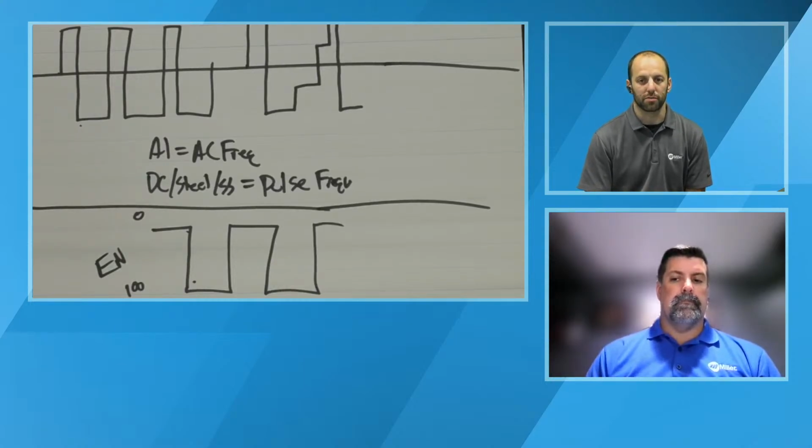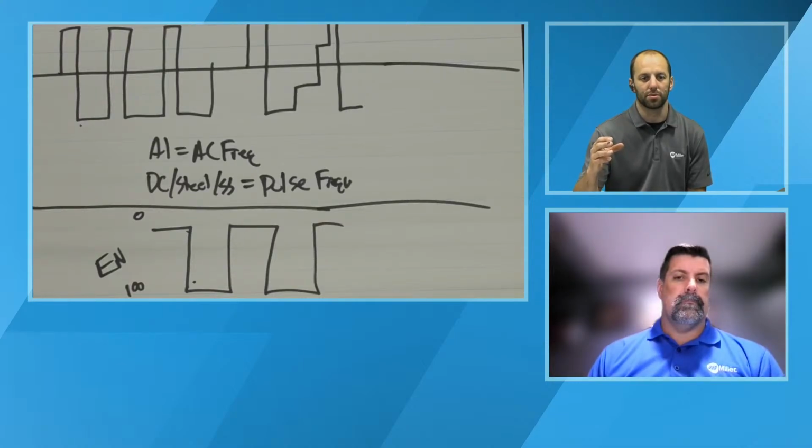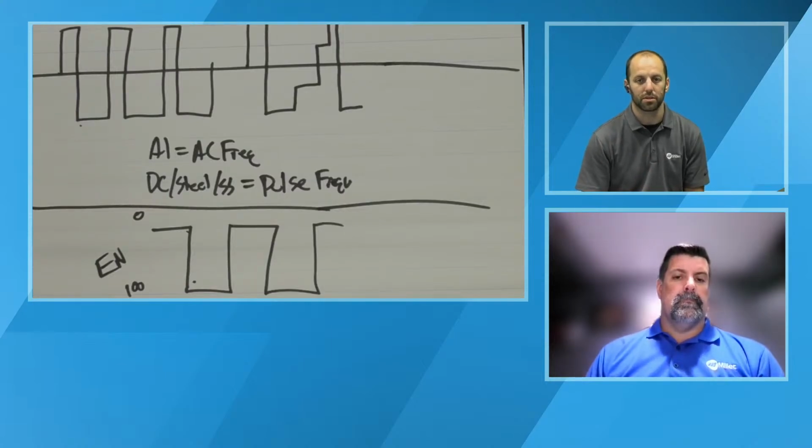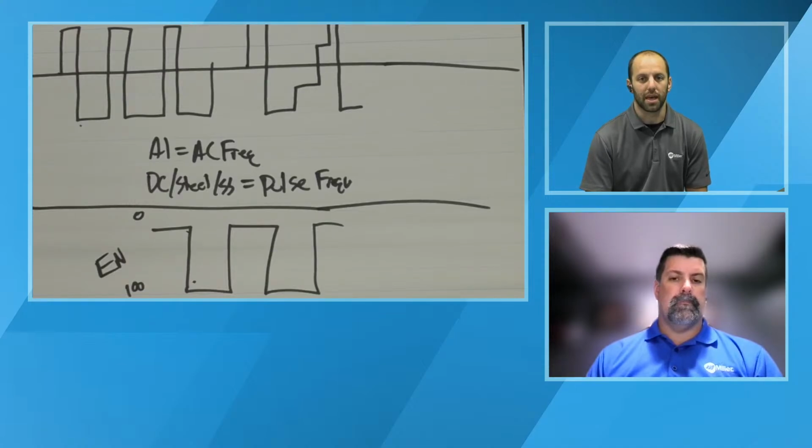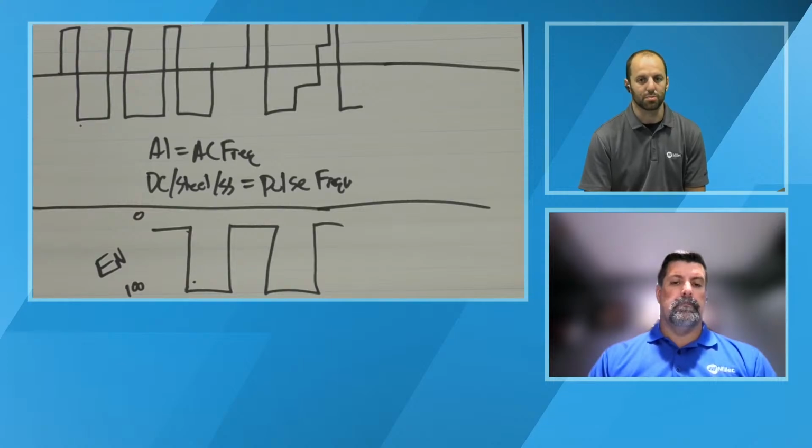You do have those periods of cooling, so if you're completely closing your weld puddle up, it can impact your ability to effectively consume that root of the weld. If you're completely closing the weld puddle up and not waiting on that next hit for the weld to consume that root, or that interface between the two faying surfaces. So it does take a bit of time and expertise to do it effectively, but it can be done. Certainly if you're looking at getting into that, you'd want to do some sort of welding procedure qualification, looking at how you're going about that, but it can be done effectively and is being done in the industry.